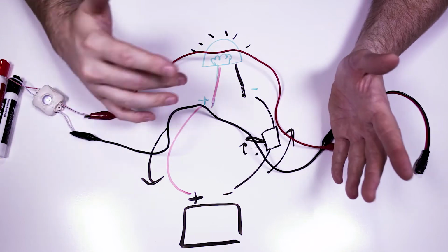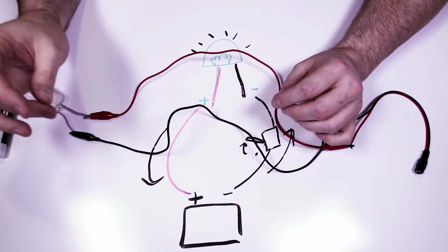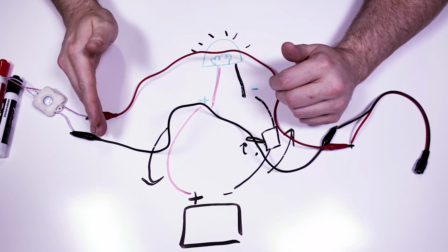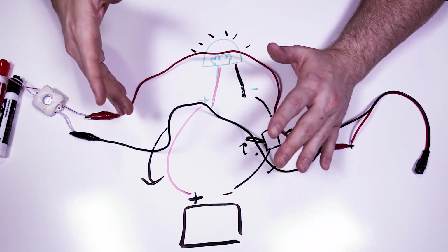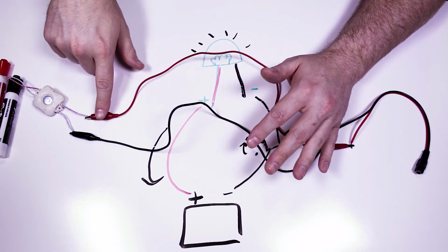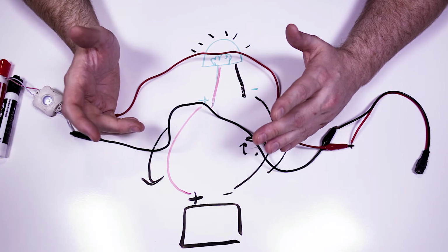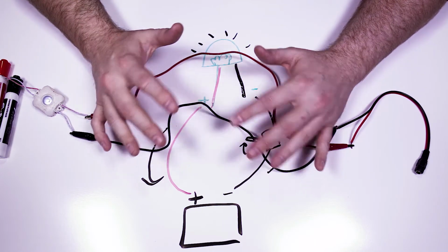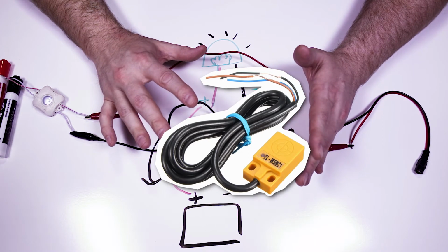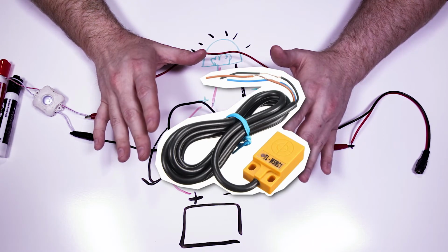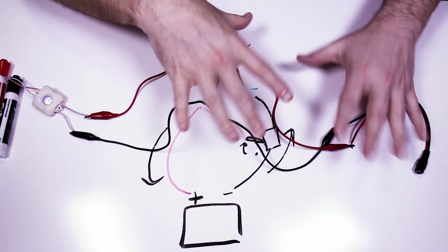However, there are some color codes that have been universally accepted for the most part. Red, for this is talking about DC, not AC. AC is a whole separate thing. But for DC power, low power, generally red is your positive, black is your negative. Unless you're dealing with proximity sensors, which for some reason, I think brown is positive and blue is negative. I don't know why that became a thing. It just is. Having said that, here's your wires connected.